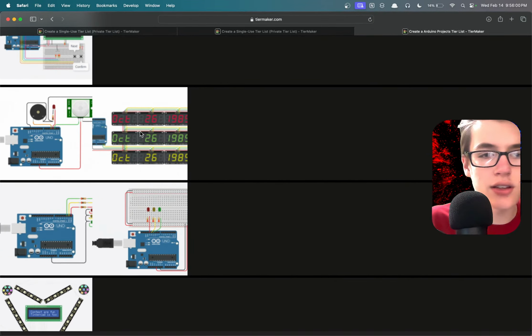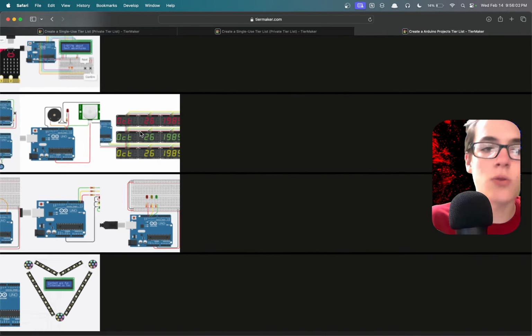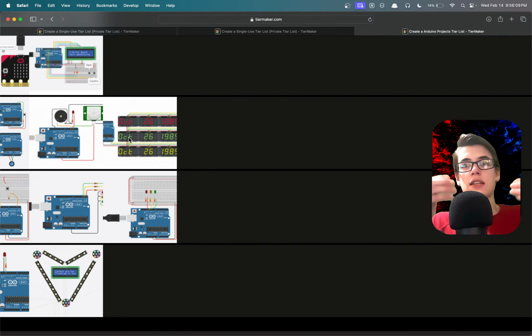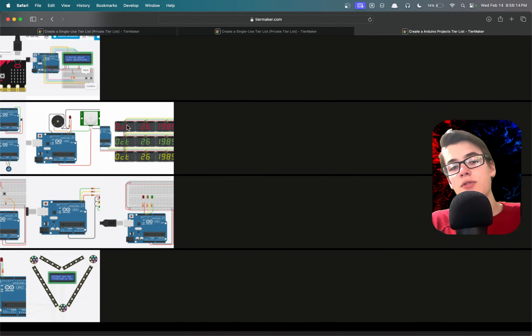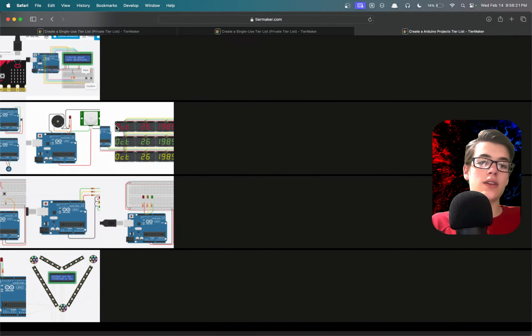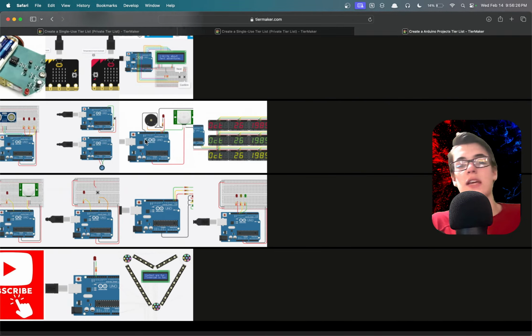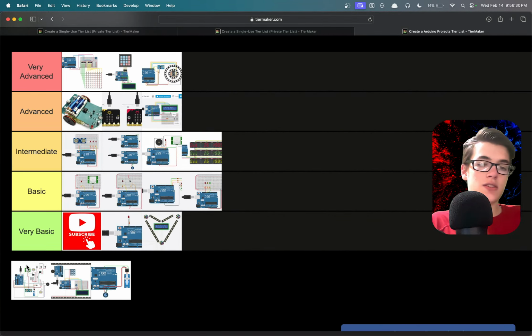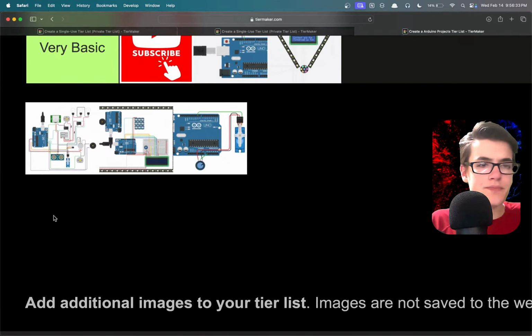Dude, actually, they're wiring a ton of these together. Okay, I see. Normally one of these modules just has a bunch of pins, and you turn the LEDs on or off using each one of those pins. But here they have those already connected to boards with a little bit of circuitry, so you're communicating with them over I2C, which makes it much easier. Instead of dealing with, I don't know, 100 LEDs, you're communicating with the little chips on the backs of each of these, and that makes it much easier. So yeah, that's probably intermediate.